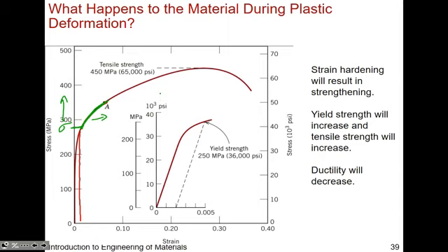So you can see when you deform a material, you actually increase the strength, because when Zachary let go of the load that he was applying, right? And so now you could think about coming back, sorry, I'll definitely get to you, just one moment. So Zachary has now deformed some material, the strain is somewhere here, he's let it go. That's supposed to be a straight line. He let it go. And now, you could see if you draw this material again, there is some plastic deformation that's restored when he lets it go. And then if you continue the curve again, you could see the strength is now increased a little bit.